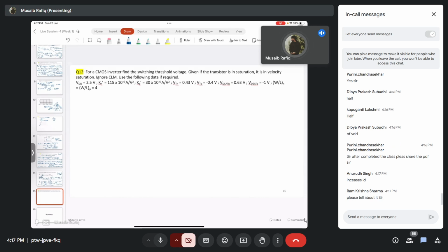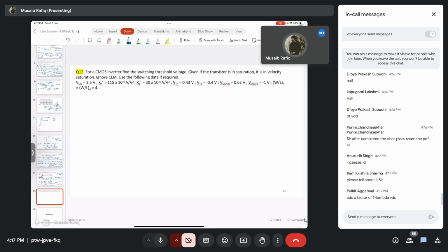So this is basically a short channel effect. From the drain side, when we increase the drain voltage, there is the lambda factor, which is the approximation of it, where lambda is your channel length modulation factor. You get that factor multiplied to your drain current equation, and you have a slope with increase in VDS. You don't have a constant current; you have a slight slope. When we increase the drain voltage in saturation, my current should ideally be constant. But what happens is my depletion region increases from the drain side with increase in the voltage. In a long channel device this doesn't impact much, but in a short channel device my effective channel length decreases, and once it decreases, my current increases, as you can see from the equation. Then we make some approximations and we get to this equation, 1 plus lambda VDS. This is not discussed in detail because it's mostly from a modeling perspective, but as a first order approximation, you can use this equation.